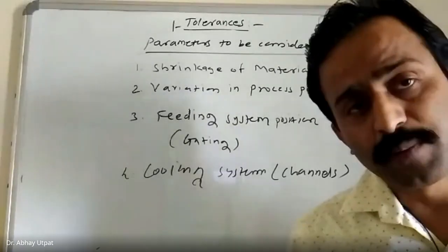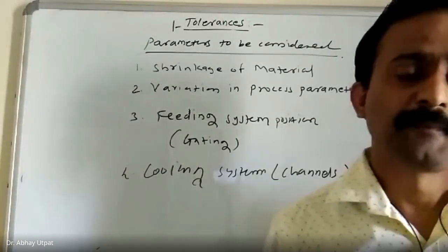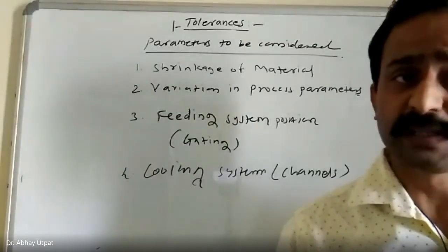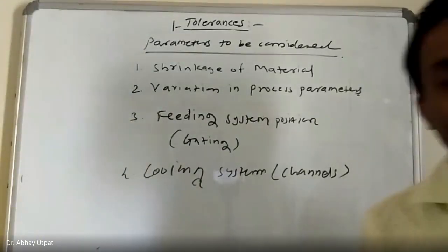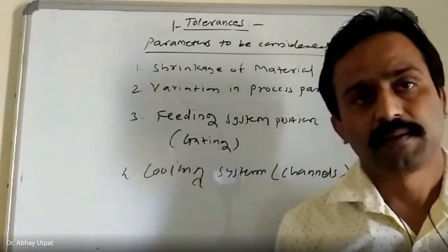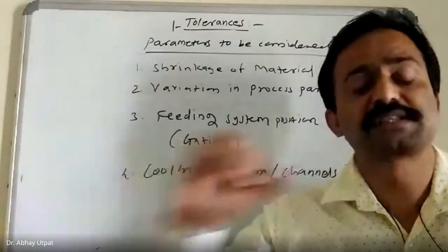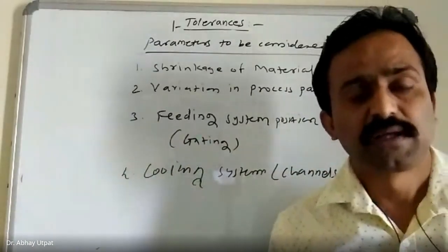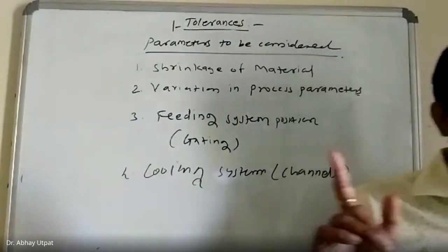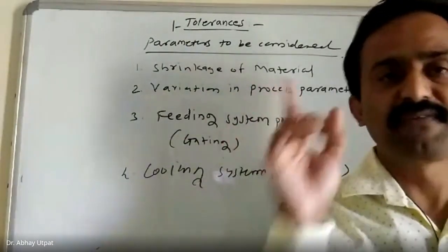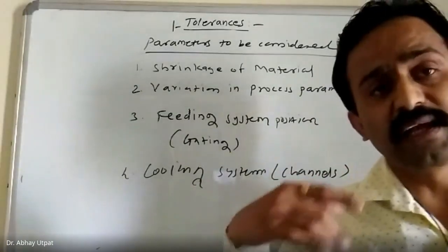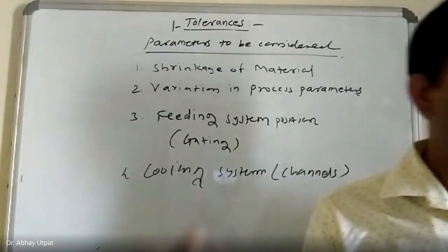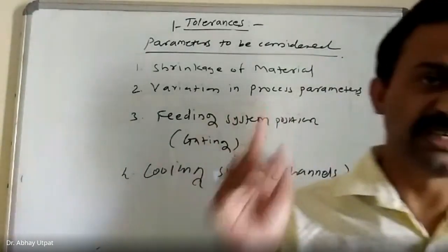Means at a time 4 components are manufactured, then it is a multi cavity mold. So what may be considered depends upon the property of plastic. In case of single cavity, if allowance is X mm, then for every additional cavity the tolerance will be increased by 5%. I repeat once again, what statement is given in case of design? If X is the tolerance for single cavity, then for every additional mold, 5% tolerance is increased.